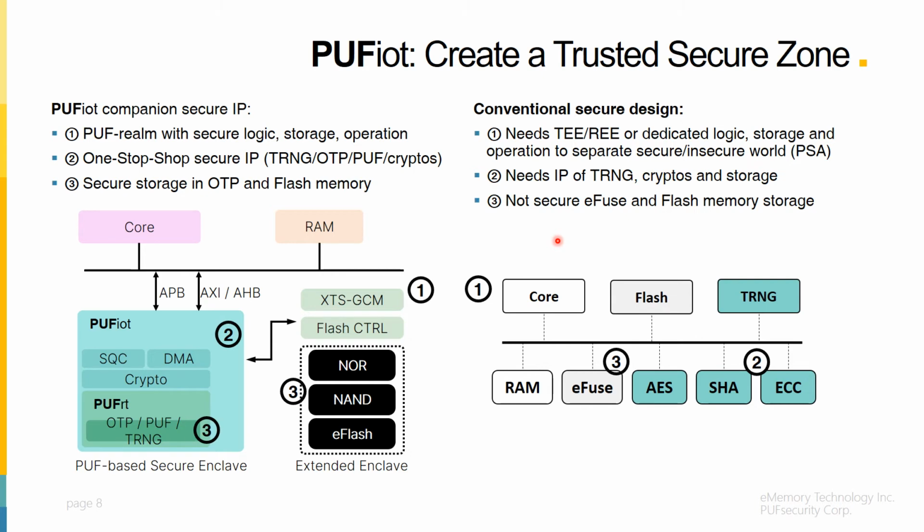In contrast, in a conventional SOC, since keys are distributed everywhere, including insecure eFuse storage, it will be a difficult task to cover all vulnerabilities. You have to do a lot of protection work on key distribution, working memory, and execution threads in core. Moreover, since there is no entropy in the conventional secure system, this means that sensitive data is not protected by any entropy.